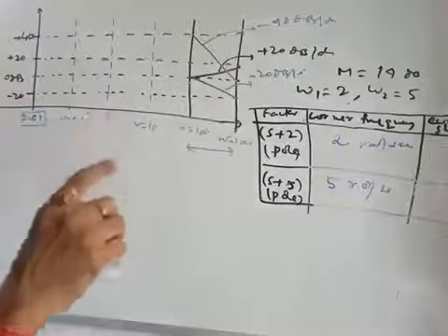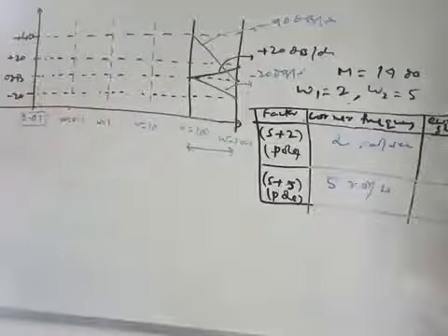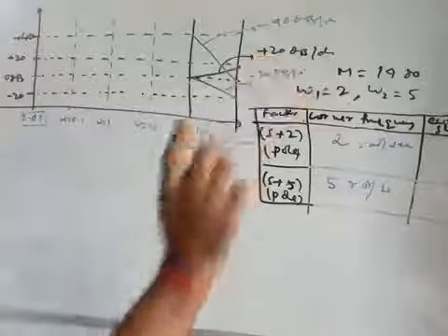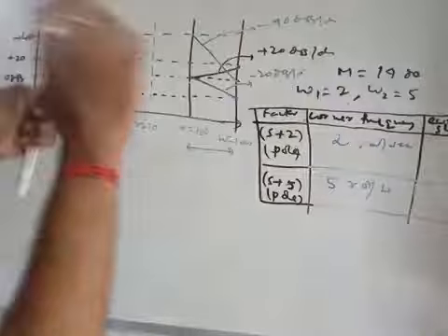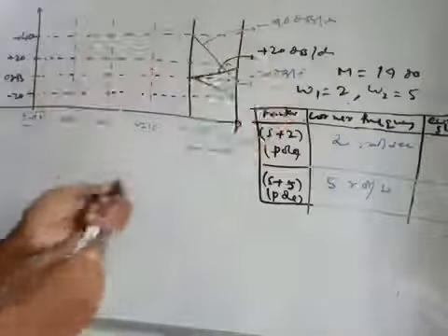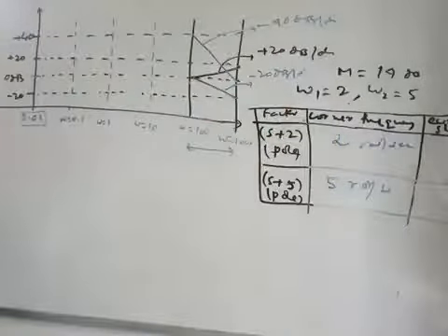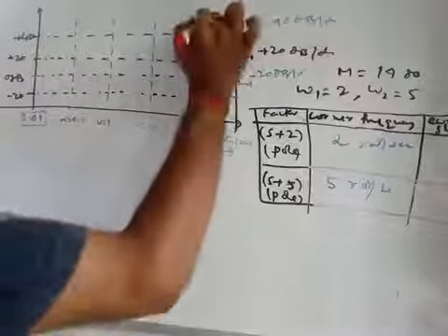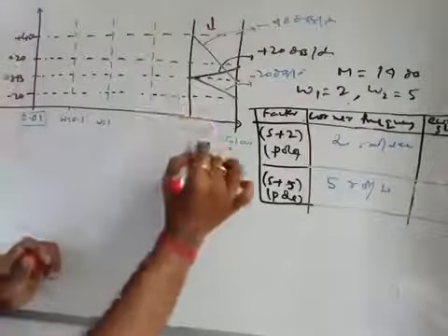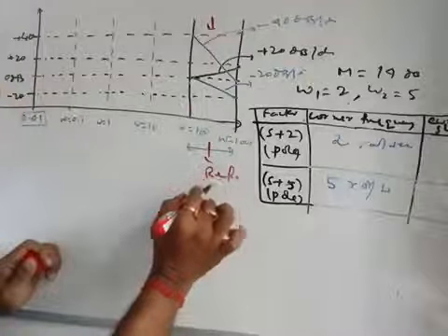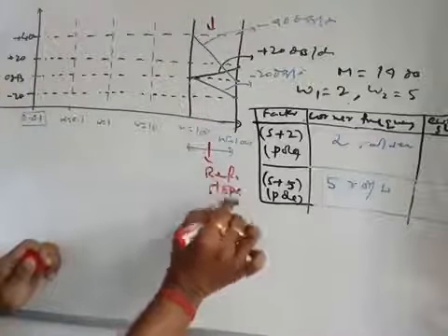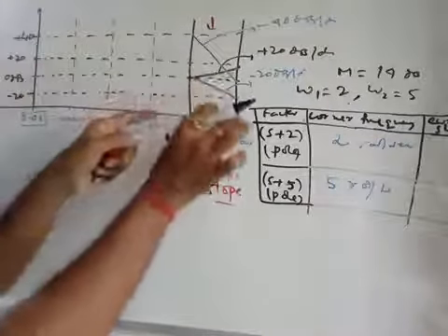So 0 dB to plus 20 dB means what you are getting? You are getting a slope equivalent to plus 20 dB per decade. Those are the different slopes you can draw here as your reference slopes. So these are the reference slopes which will be drawn at the rightmost decade, right?